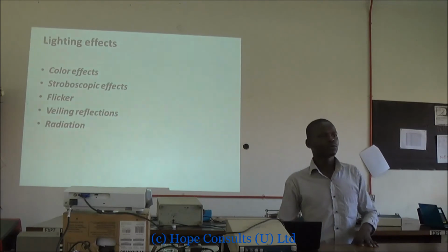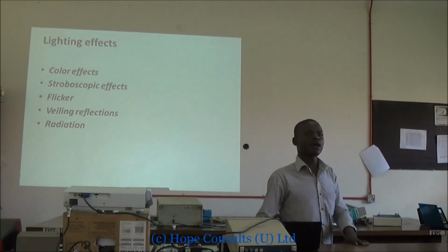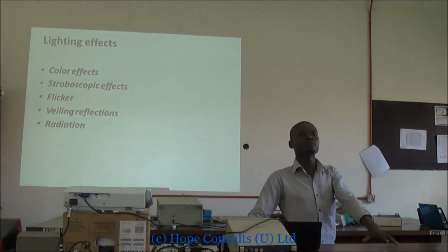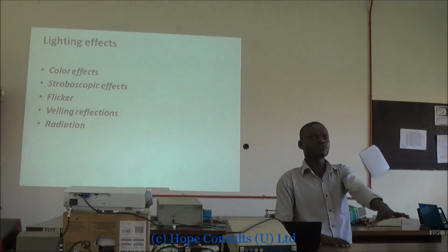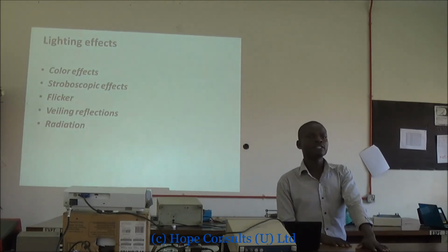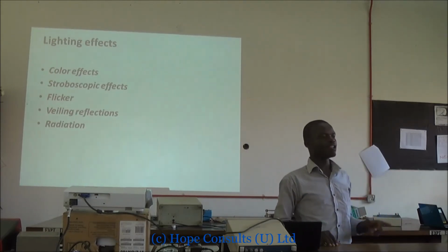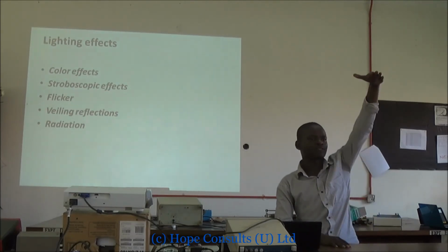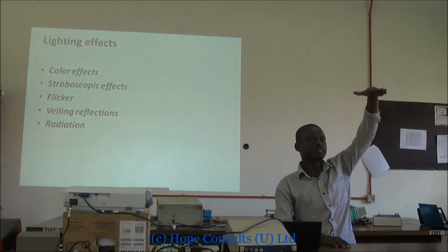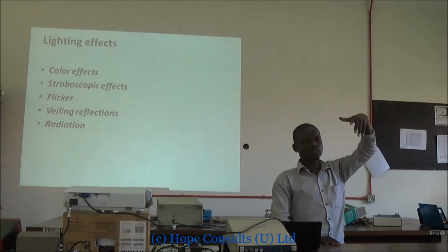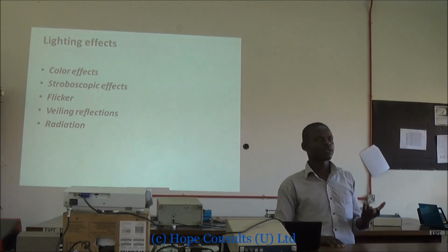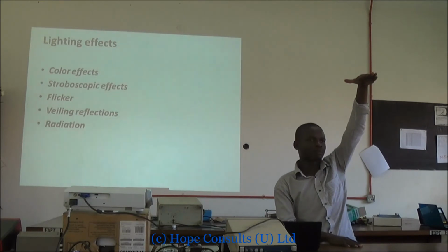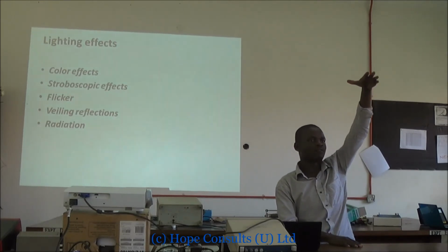Then to wind up, we're looking at how the assessment is done on a horizontal surface. We were talking about the walls, but it is done on a horizontal surface, on a work plane. For instance, if this is a room, measurements are made all over the whole room. Then they are divided into small squares. Then the height from the bottom to the surface where the lighting system is going to be placed is measured, and normally is taken to be around 0.8 meters. For instance, if the table is up, something like 0.8 meters, a minimum of that.